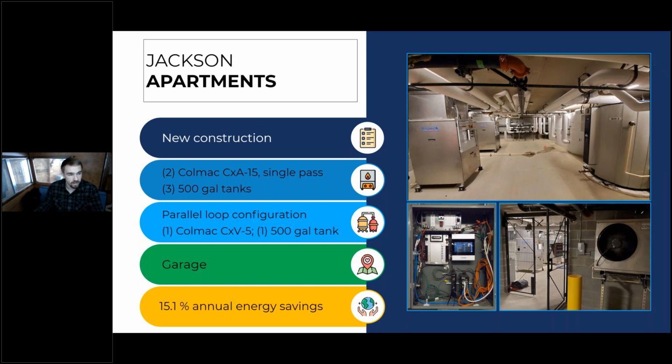We also have a parallel temperature maintenance tank, which is handling those temperature maintenance losses that were addressed in that feedback, because heat pumps have a difficult time reheating warm water up to a really high temperature, as you would see with the water that circulates through the building. We send it out hot and it returns slightly cooler, and the heater has to reheat that to a high temperature to make sure that the water in that loop never goes cold.